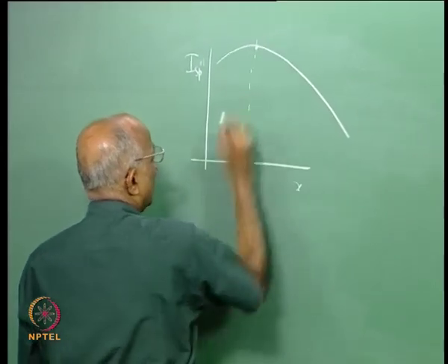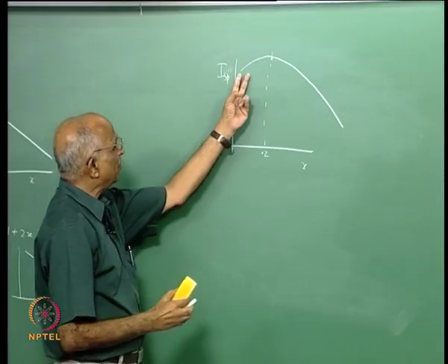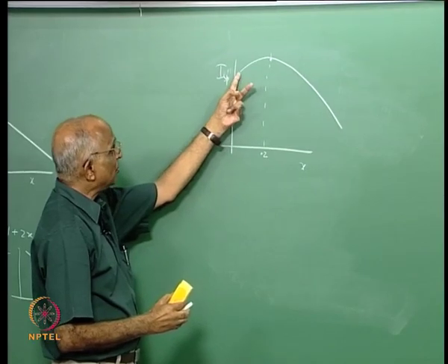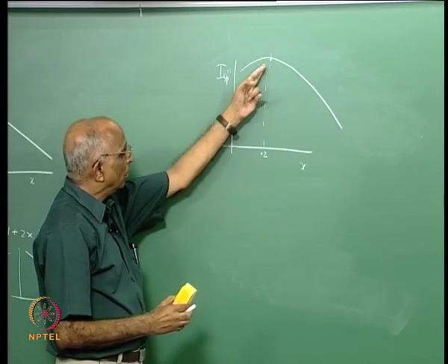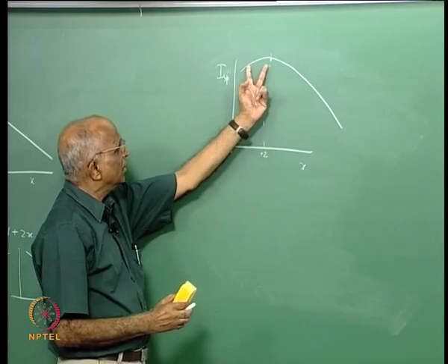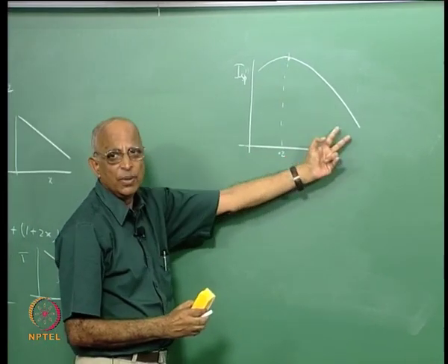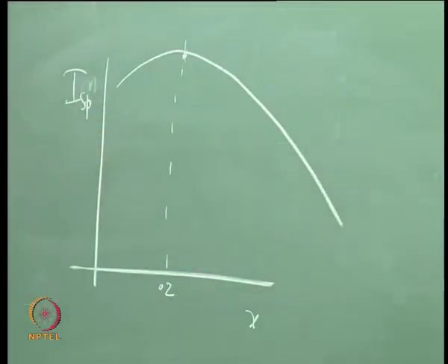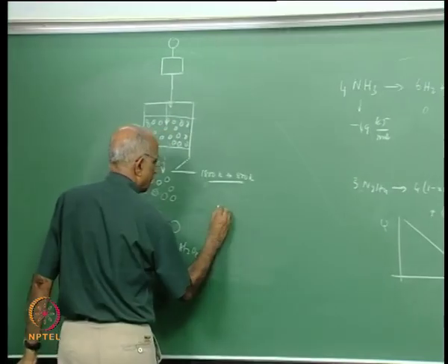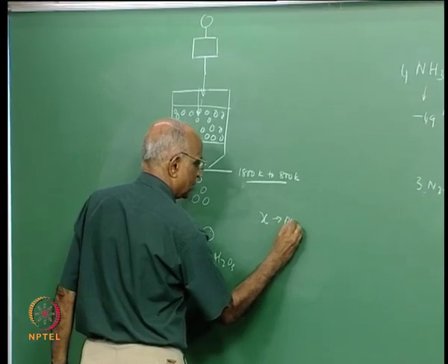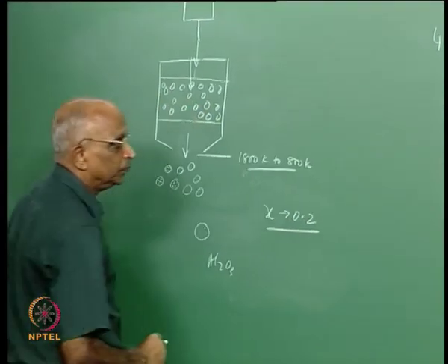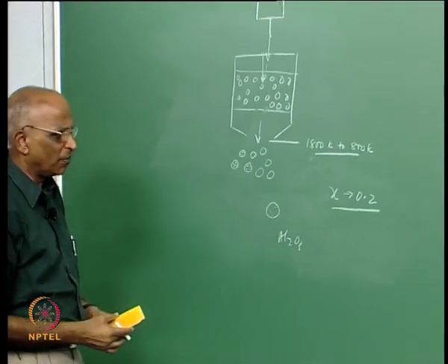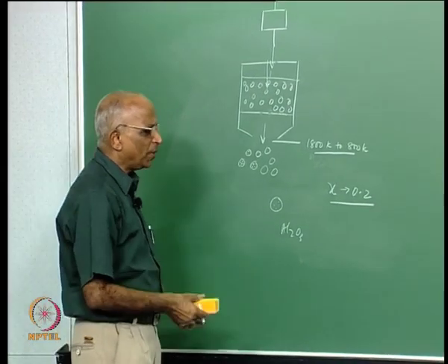I get a maximum value around this. The change in specific impulse between 0 dissociation to 0.2 dissociation does not change much, but thereafter it begins to come down. Therefore, you would like to configure your catalyst bed such that you have degree of dissociation as 0.2, and that is when you get your maximum performance. This is the background for monopropellant rockets.